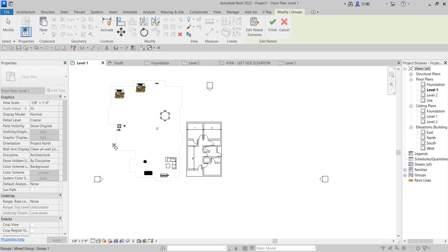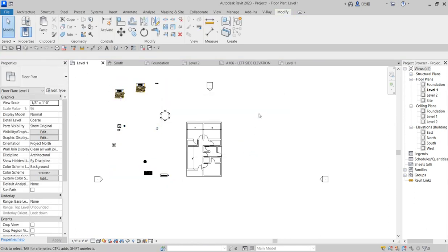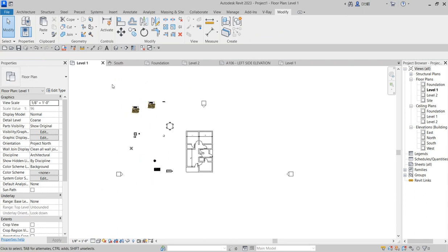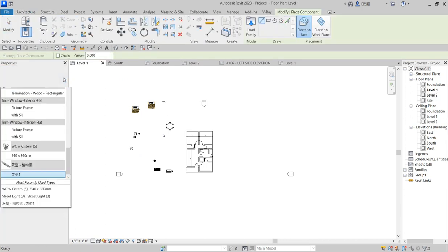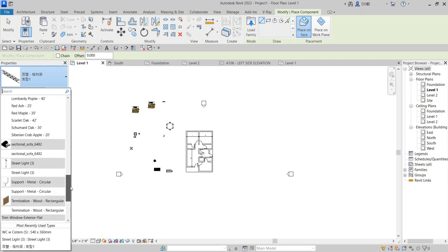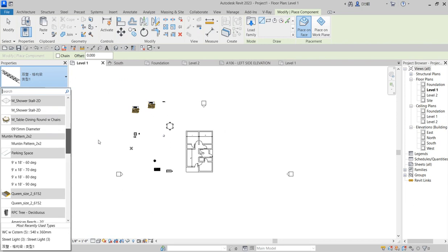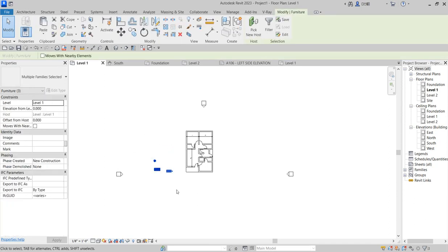So this is the trick. You bring everything here, and you can delete the ones that are not having anything to do here. Like if you select a component now, good components, you are going to be seeing all these elements you have brought. Can you see all of them? The chair section, the lighting, the bed, they are all here now. So you can now just delete them here. If you delete them here, that does not say they are not going to exist again. They're already part of the project.